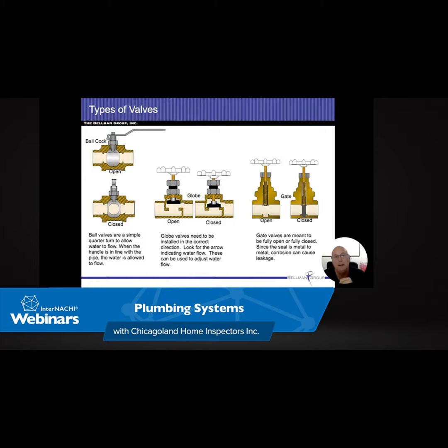Inside the flue of that water heater is a baffle, and it's nothing but a twisted piece of metal. So as the hot air goes up, it's going to bounce left, bounce right, bounce forward. It keeps pushing the heat to the different sides of the walls as it's going up, and that just helps heat the water faster. It gives more direct, not necessarily flame contact, but heat contact when it goes up there.